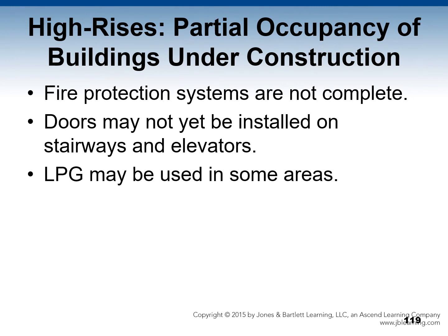So with high rises, let's talk about partial occupancy of buildings under construction. It is dangerous to have a building partially occupied and partially under construction, but it happens. Fire protection systems are not complete. Doors may not yet be installed on stairways and elevators. LPG or combustible liquids may be used in some areas. So there are a lot of hazards.